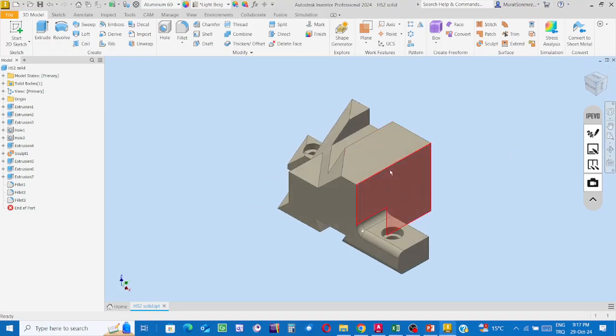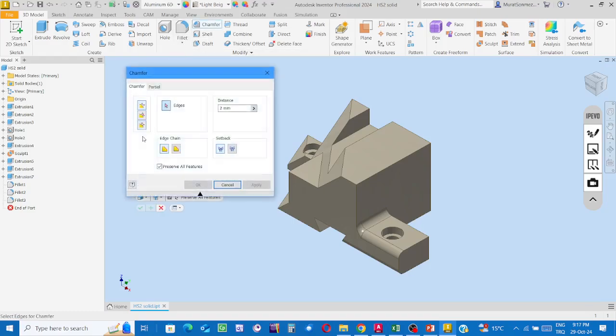Then, create a chamfer along this edge. In Inventor, that is the push button to click to start the process. I am going to create the inclined surface. Its inclination angle is going to be 45 degrees. So chamfer distance over that surface is the same. Let's say 4 millimeters is the chamfer distance. And then indicate the edge, and say OK.